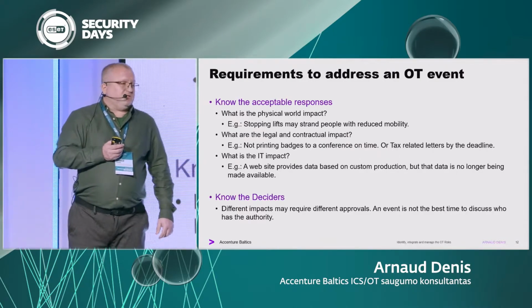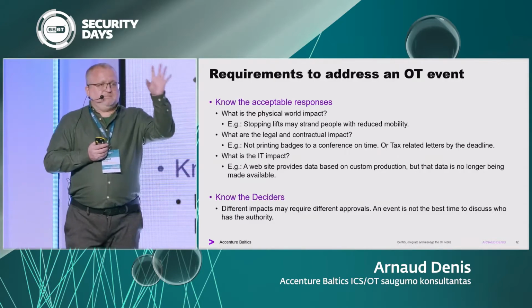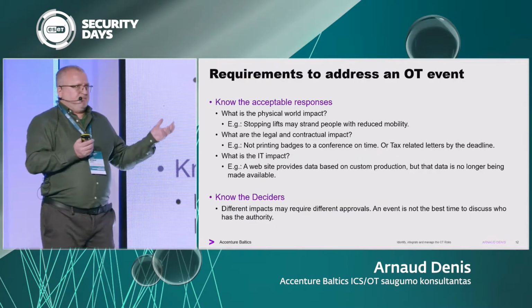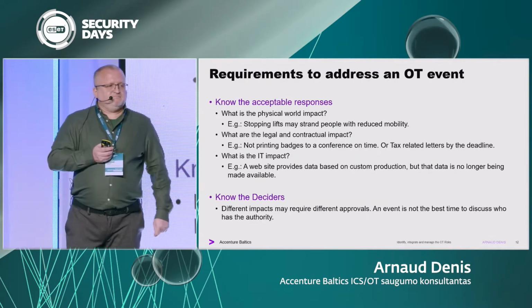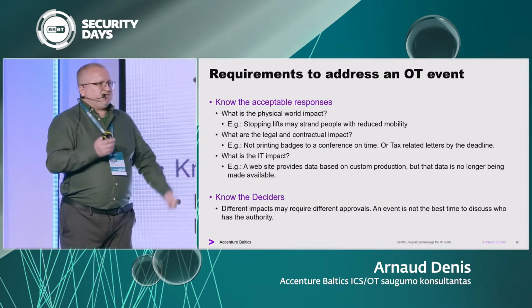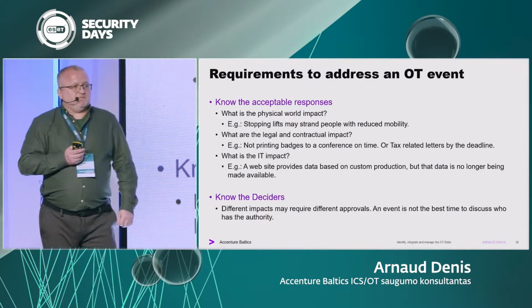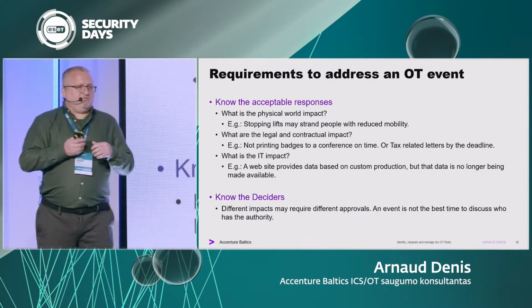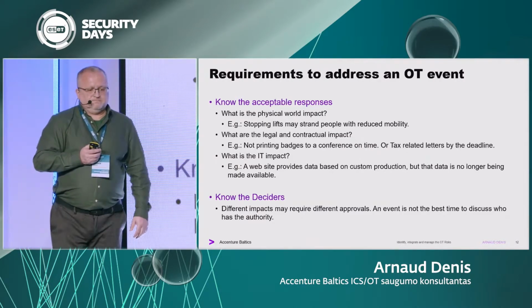And finally, you want to understand the IT impact. Can something in the OT go to my IT? A typical issue is a maintenance guy coming in with a USB key, plugging it in to do some maintenance. A very, very common occurrence. The problem is if you don't have something separating your IT, or if you don't have the right controls in place for an incident, it might propagate.